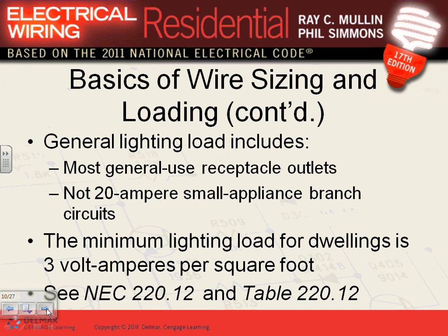For this project, here's what we're going to be doing. We're going to follow the code, and you're going to use 15 amps unless the code asks you otherwise. Unless the code specifically says a 20 amp circuit, for example the kitchen, you're going to be using 15 amp circuits. Did you guys hear me? Because you're in my book, and I'm the authority having jurisdiction here, it's overkill to use a 20 amp circuit, for example, in a dwelling. Did you guys hear me? Not here. To feed the lights in the hallways and in the kitchen and so forth.